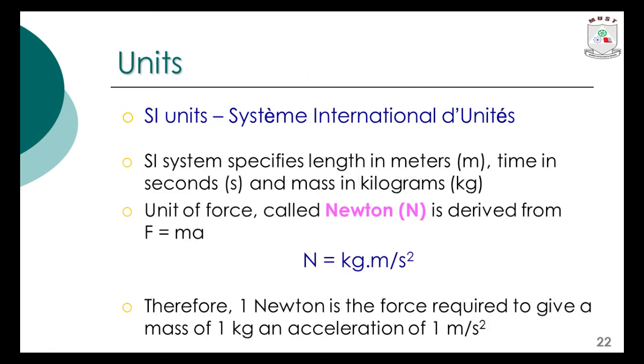So finally, we're going to be dealing with units and systems of units. Like we saw in the introduction, force is not a basic physical quantity; it's a derived quantity. For example, force has the unit Newton, which is represented by the uppercase N, and the Newton can be re-expressed in terms of the basic quantities of mass, length, and time. So the Newton becomes kg·m/s². Kg is mass, meter is length, and second squared is time, dimension of time by dimension of time.